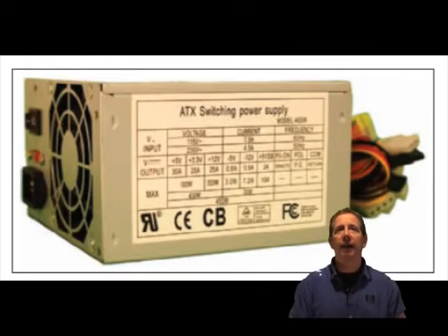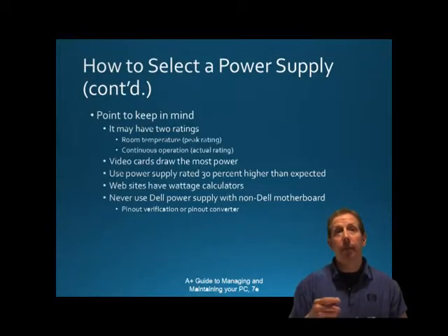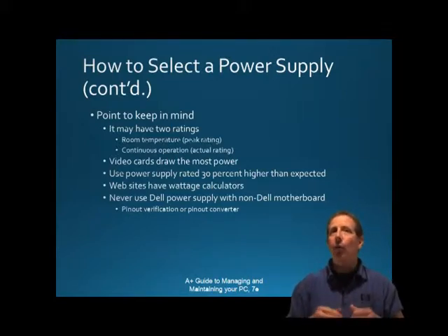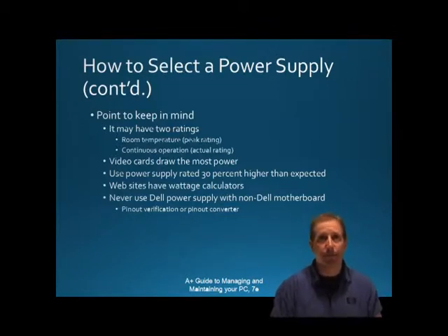Use a power supply that is rated about 30% higher than you expect a system will use. Power supplies run less than peak performance, last longer, and don't overheat. In addition, a power supply loses some of its capacity over time. Don't worry about the higher rated power supply using too much electricity. Components only draw what they need. To know what size power supply you need, add up the wattage requirements of all the components and then add 30%. Device technical documentation might give you some more information about this.